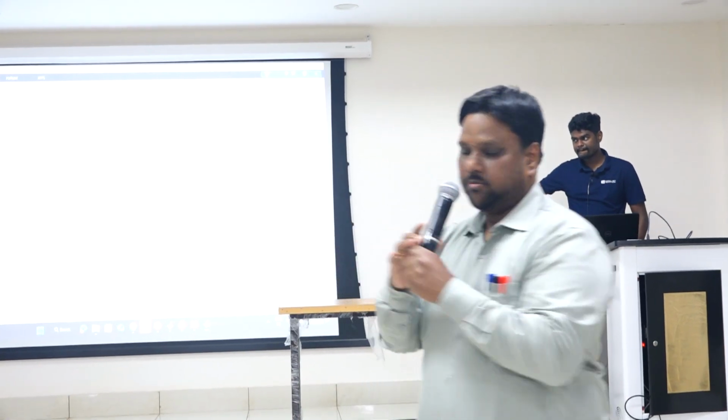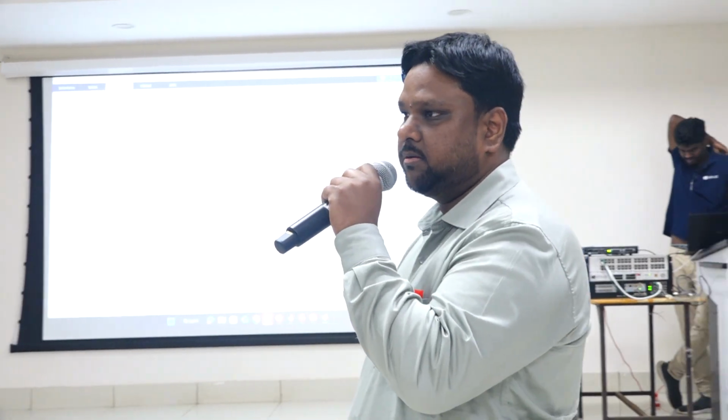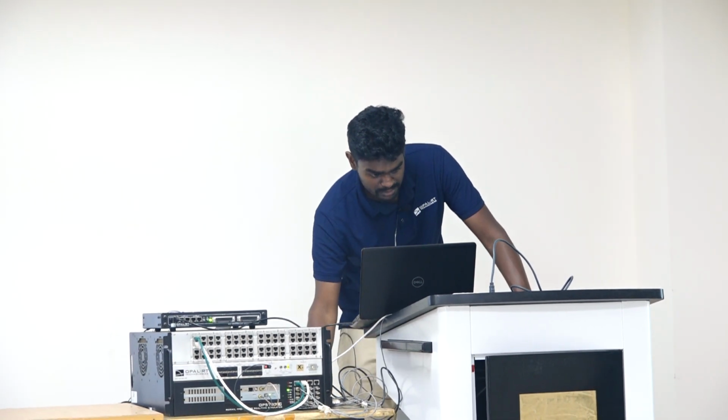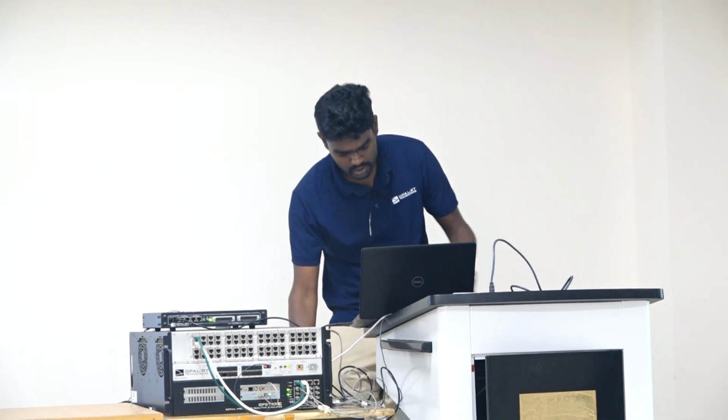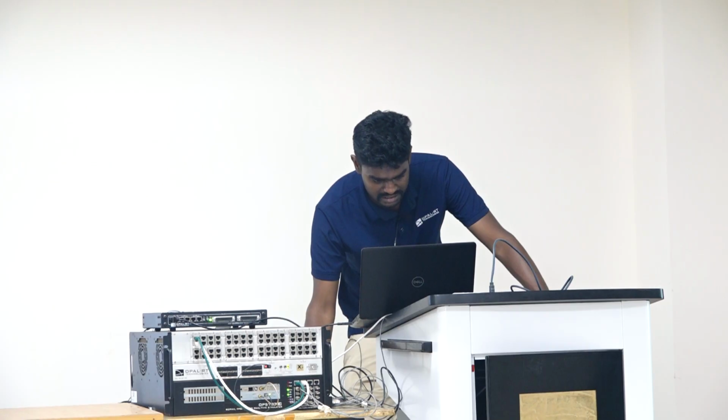Whatever you see here is the power circuit, and in control system language we call it the plant. To link the external controller with this simulation, you need to send some feedbacks to the controller. Currently your controller will need the 3 grid voltages and also the currents, after the filter and before the filter. So all these feedbacks we need to send.